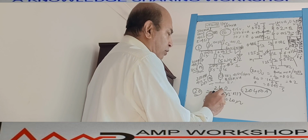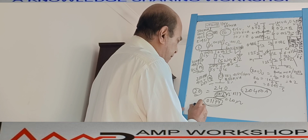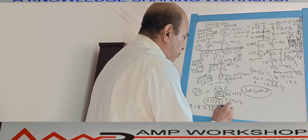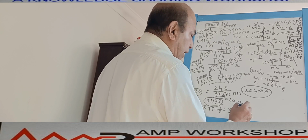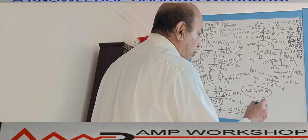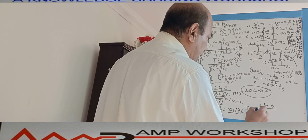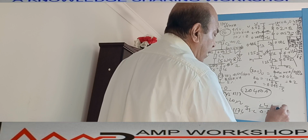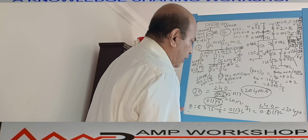We rounded it, but actually the original, if you recall, Z equal to 85.15, and if we make 1 by Z, that comes to 0.01174. Okay. So then we calculate I short circuit. How did we calculate? 240 phase voltage divided by that per phase impedance, that is 0.01174. If you calculate this, it will come 20,400 ampere. That is what we got last time. Okay. So we will see now how much we can get from here.